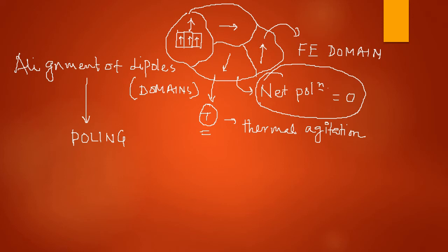So this is an essential process in converting an inactive ferroelectric polymer into a useful, electromechanically active one. The poling process is basically an electrical alignment process. Before poling, a material is electrically inactive.